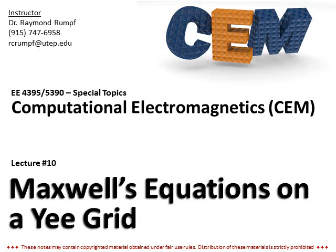And this is very, very important: to understand the Yee grid, the placement of the field components within the unit cell, and how the finite difference expressions are derived. It's a little bit crazy, but in fact, numerically, it's a lot more efficient and very elegant.